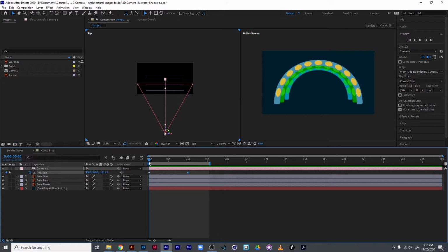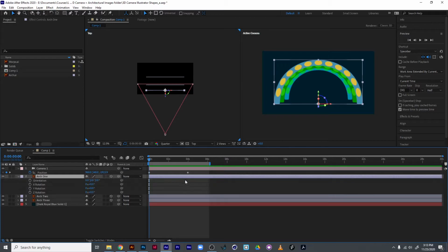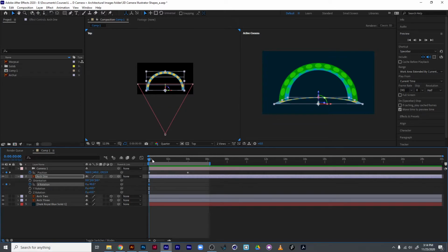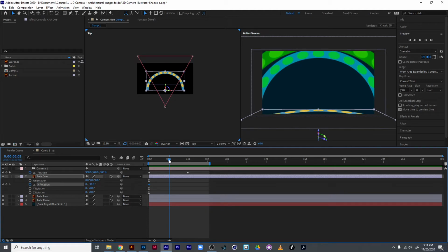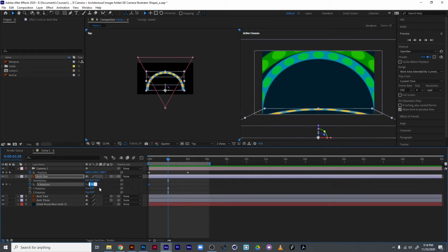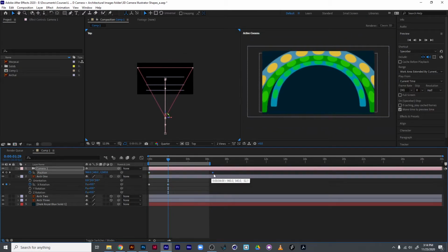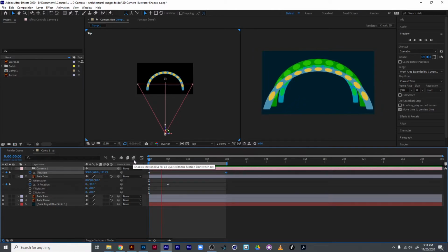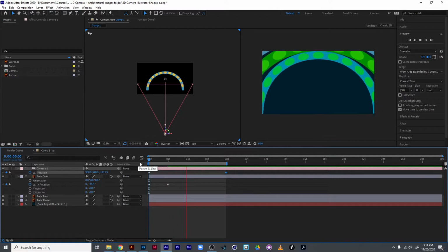And so this sets up some nice precedent for us, right? Like if I wanted to animate this one so it pops up as we're passing through it, I can animate the X rotation. Maybe I want to start with it totally down. Let's do -90. And it will then pop up to 0. So it'll slowly rise up, and we could offset this or slow this down just slightly so we see that a little bit more closely. So now as it's going, we've got some animation moving along with it.